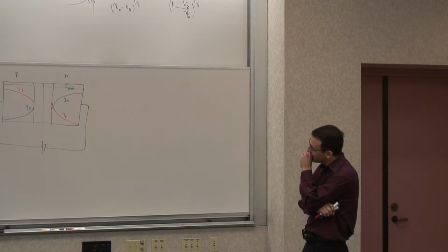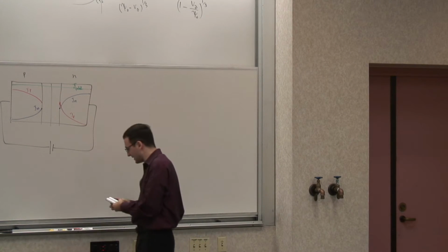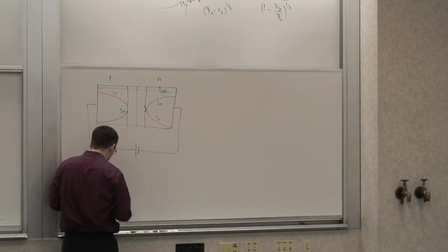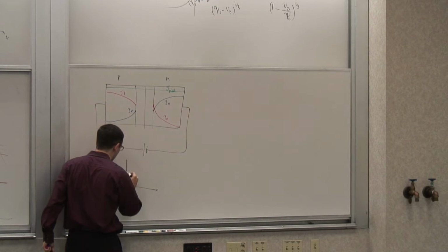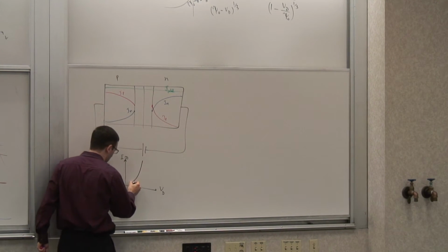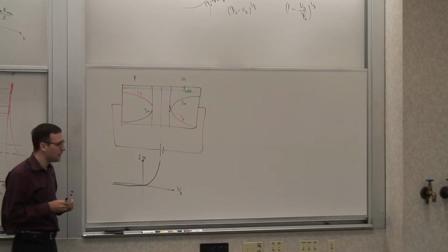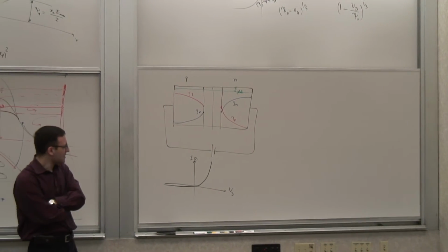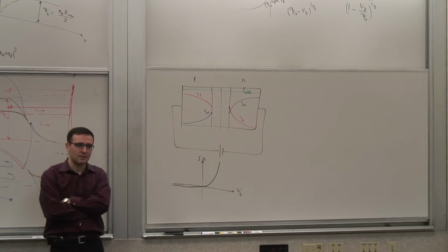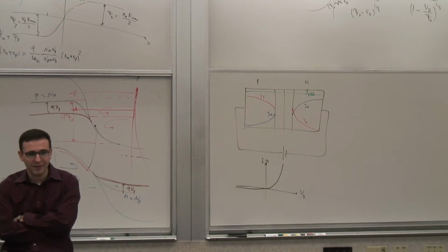Well, think about this. So far I've created this device that has this IV characteristic that looks like this. It's got exponential behavior. So if I look at ID versus VD, it is an exponential like that. Okay, more or less. Now, it's useful for certain things. If you want to make a rectifier, for instance, you can make it and all sorts of things. But it's not a very good amplifier.